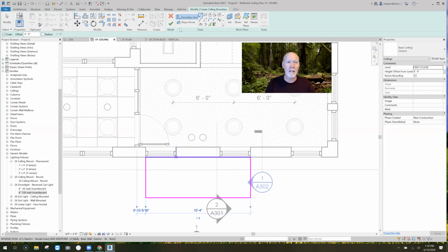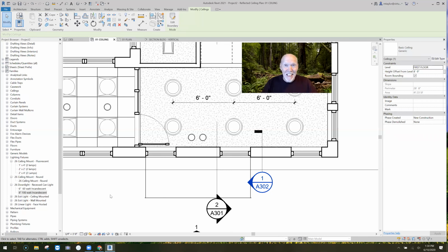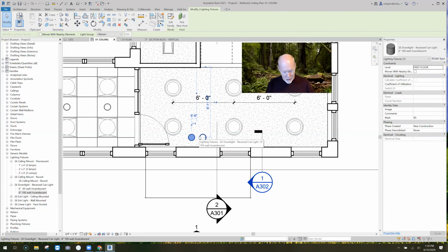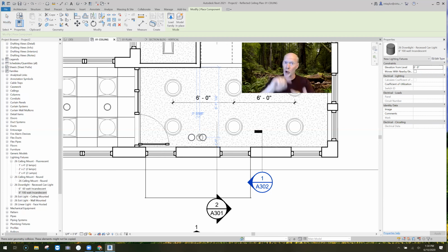and I'm going to put my ceiling right here, exactly where that roof is. And it's going in at 8 feet. But you can't see it because it's just a plane, and it doesn't have any texture to it. It doesn't have any materials to it. It's just a plane. And so now, if I pick one of these light fixtures and type CS on my keyboard for create similar, take a look.